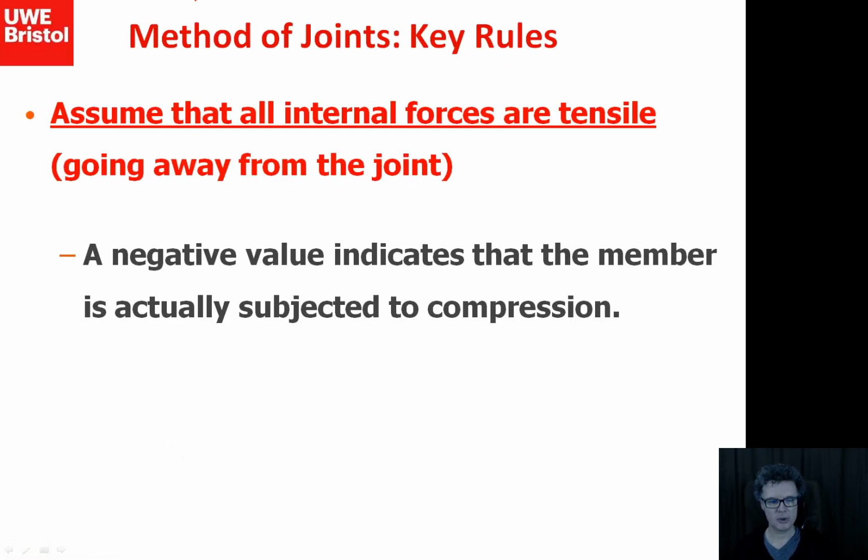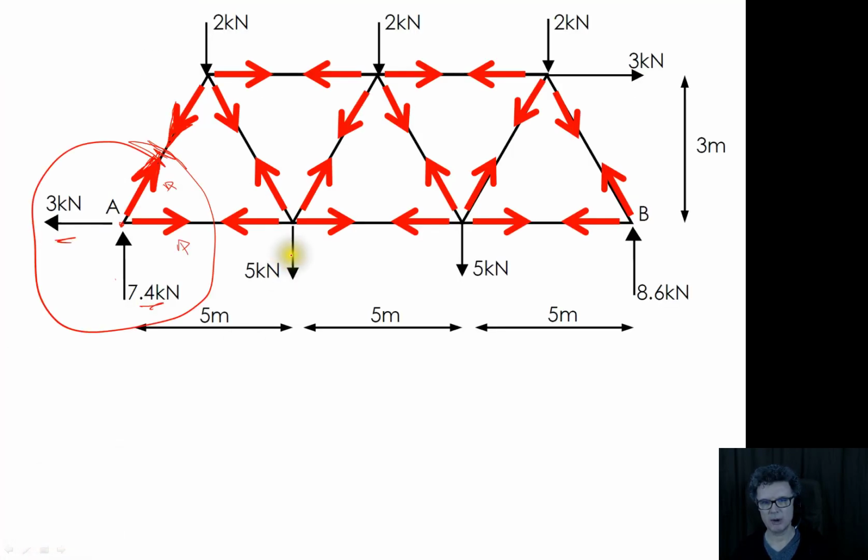So you notice on that framework what I decided to do was, for each member I had the forces in each bar pointing away from a joint. So if I'm pulling my member apart, the internal forces will be going the opposite direction. They'll be going that way. So if I'm pulling them, internal forces will be going that way.